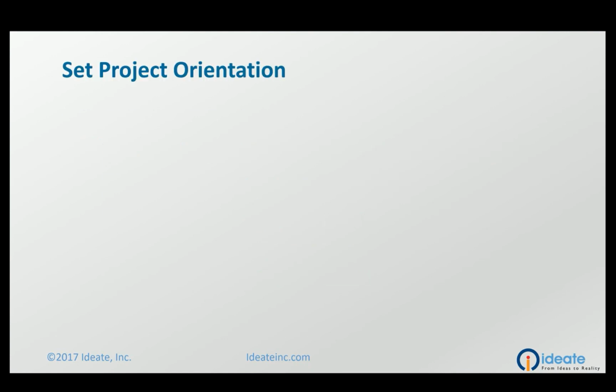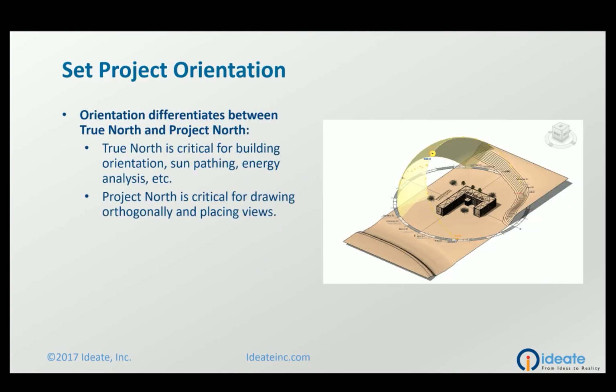All right, and sometimes I like to just show PowerPoint stuff, but I will be getting into the Revit model here in just a moment. So the first thing I wanted to go over is the importance of setting your project orientation. And the reality is, and we've talked about this, I cannot stress and emphasize enough how important it is to have a BIM execution plan in place and coordinate all of your project base point, your survey point, your coordinate system stuff, even before you start thinking about modeling anything in Revit.